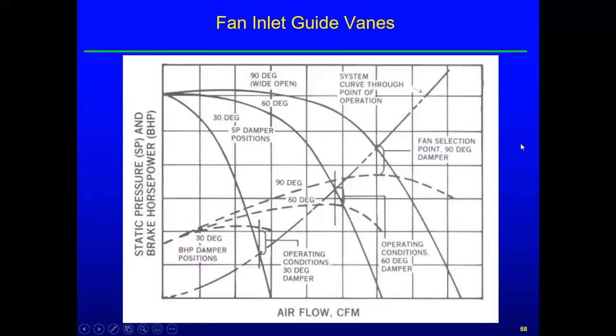This is pretty nice. This is why I put these in here. This shows what happens with the inlet guide vanes. So the inlet guide vanes actually recast the fan curve at every different degree opening position. So we draw 3 of them here. So wide open, 90 degrees, this is our fan curve.